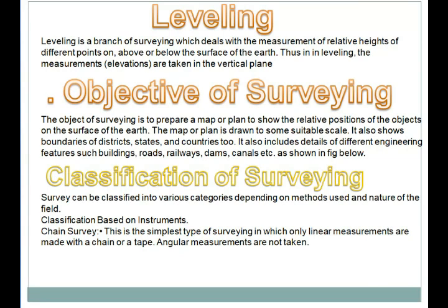The objective of surveying, along with the classification of surveying according to the method and the nature of the instrument that is used in the field. We'll discuss the term leveling. It deals with the relative heights of different points on or above the surface of the earth. Thus, leveling is the measurement of elevations that are taken in the vertical plane. Vertical plane means the ups and downs available on the ground.